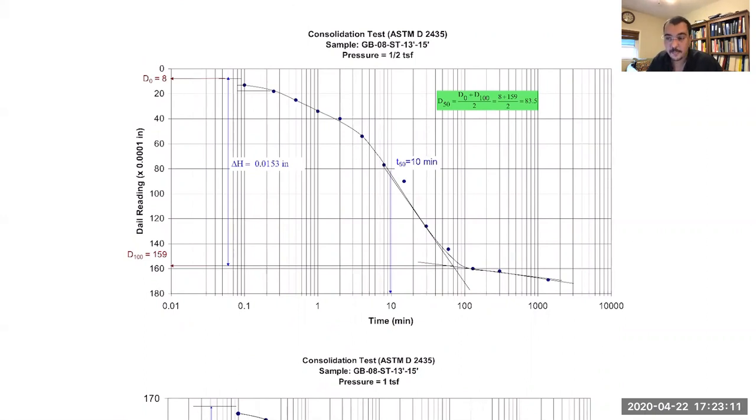the T50. And remember, we need the T50 because Cv, the coefficient of consolidation, is equal to T50 multiplied by what? What is it multiplied by? The drainage height squared, and that is divided by t50, right? Yes. So from this graph, you can get t50.